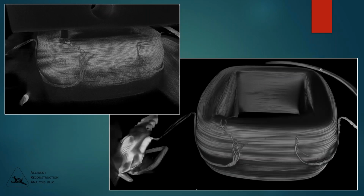And then if we go to the next slide, this is the coil in question on the left with the core still present, and then showing the coil after we have removed the core. So again, note the difference in the resolution on the magnet wire on the 2 images. This was not completely non-destructive because we had to remove the core, but by removing the core it did allow us to image the details of the coil windings much better.